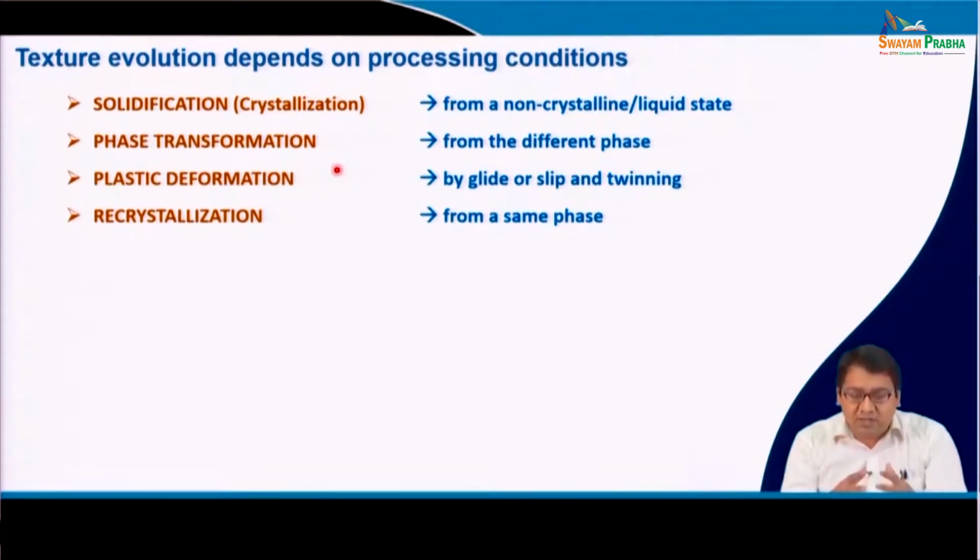Then also the orientation relationship between the body centered and the face centered or the hexagonal close packed material is maintained by some rule, say for example, the Kurdjumov-Sachs law or the Burgers law. And depending upon the previous processing history of this material, the texture is maintained based upon this law. Therefore, the phase transformed material will possess some kind of texture.